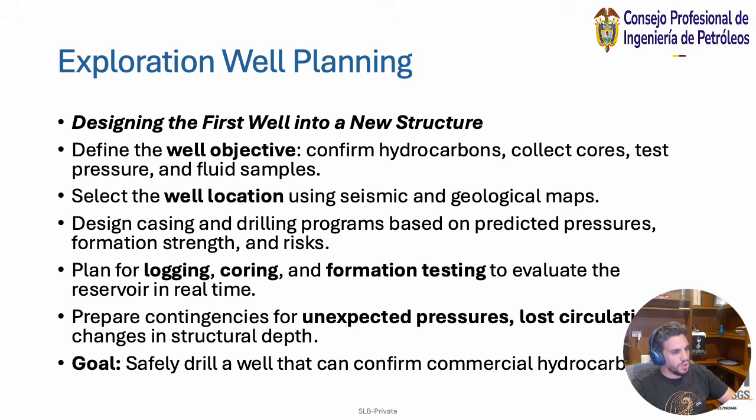So what a drilling program is, that's the next category. But when we go through this well, we find out the drilling programs, and it will also tell us a lot about how well we can log, how well we can do formation testing to evaluate the reservoir in real time. It will also prepare us for the first set of unknowns: unexpected pressures, lost circulations, or changes in structural depths, right?